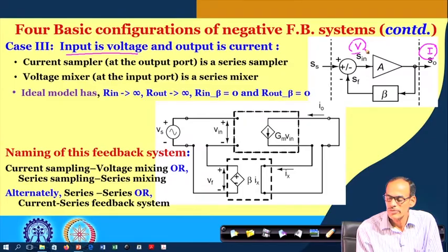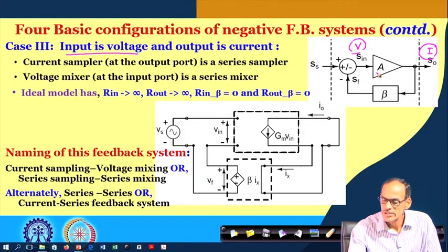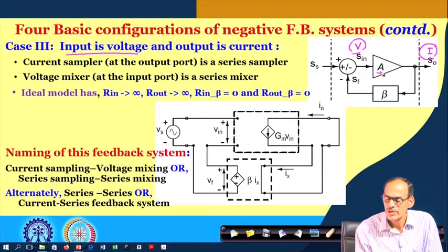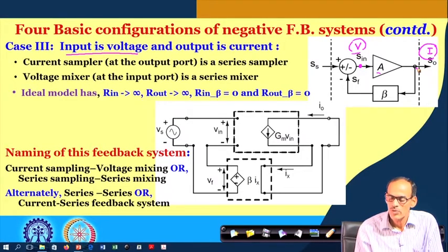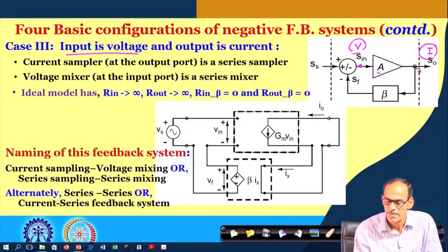So, now you need to be a little alert that this is, of course, converting voltage into current. So, this should be transconductance, which is taking the voltage at the input and giving the current at the output, that is why trans, and since its unit is mho, it is conductance. So, in the model here, if you see, instead of A here, I do have G m, where M represents trans and G represents conductance,